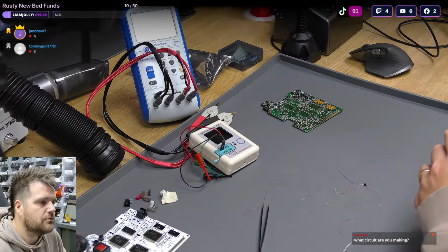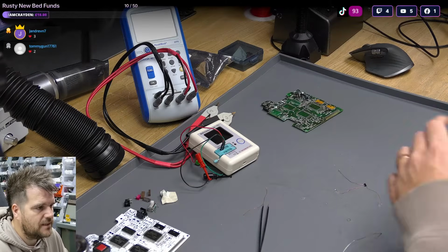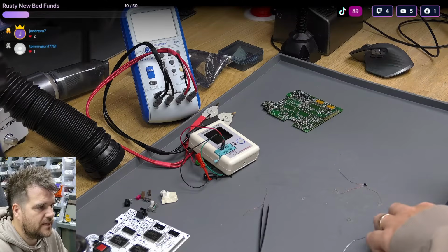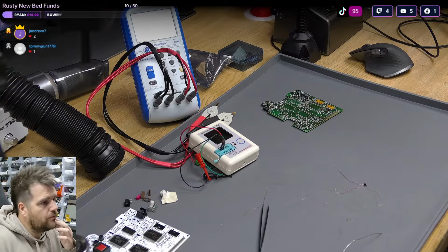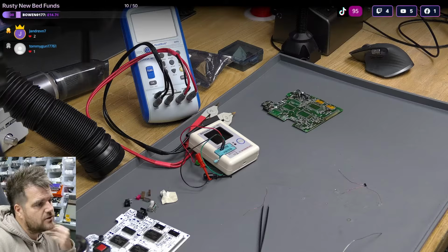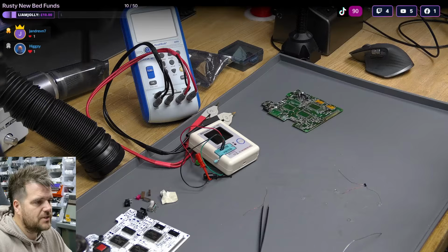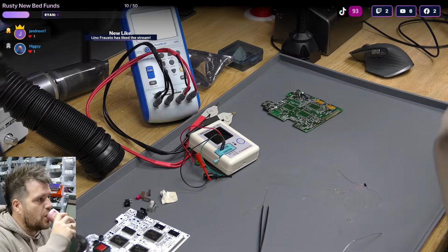If you still definitely don't, then you need to start going through that reading game cartridge wiki and testing every single pin is good. Basically, you're looking for a broken trace between the Z80, the A6 and the game cartridge slot. You'll likely have a bad trace between them. Or, unfortunately, with no screen to see what's going on, you could also be dealing with bad ASICs, and it's almost never the CPU. It could be the Z80 and it could be the VDP on the right. We've seen the VDP fail tons, but most often no sound is one of those traces, the game cartridge slot or the Z80 being bad.